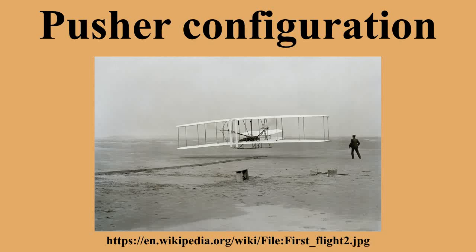Due to a generally high thrust line, negative pitching moment and sometimes absence of prop wash over the tail, higher speed and longer roll is required for takeoff compared to tractor aircraft. Main gear located too far aft may require higher takeoff rotation speed, or even prevent the rotation. The routine answer to this problem is to lower the nose of the aircraft at rest such that the empty center of gravity is then ahead of the main wheels.